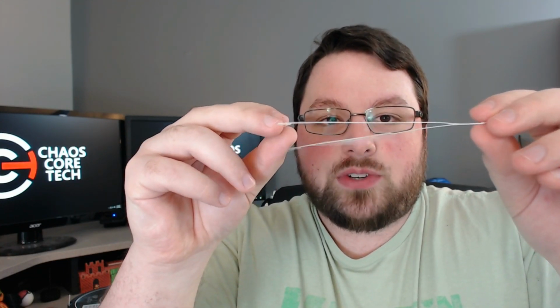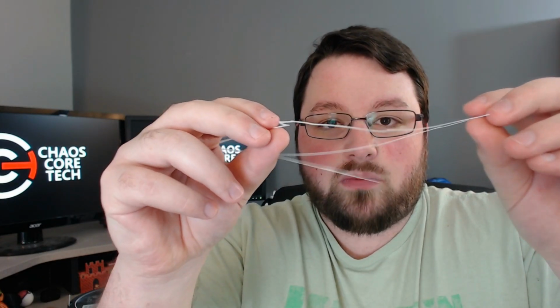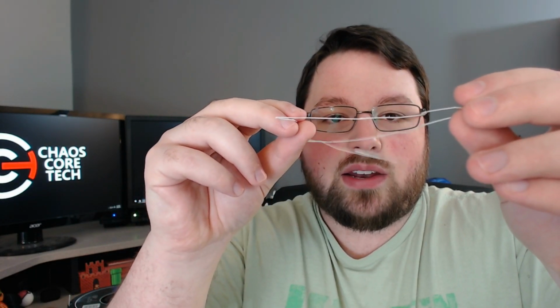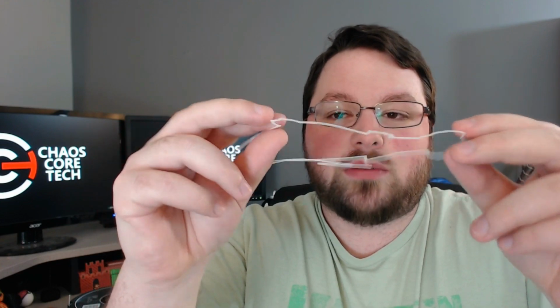And as you can see, it is pretty well squished right there, and I've never really had any problems with getting the first layer to stick or anything like that. And then once the print has finished, I tell it to cool down because it leaves the bed heated. And I found that once the bed cools down to around 35 degrees Celsius or something like that, the print will actually pop off of the bed on its own. And so I think that's kind of cool.